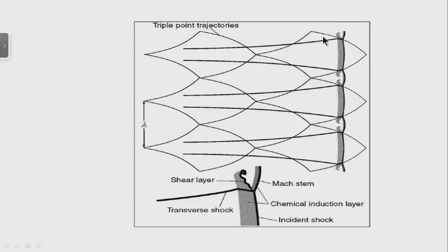Therefore, when the number of transverse waves is smaller than some limit, it is just not possible to propagate a detonation wave. In other words, if the number of cells of detonation in a particular region is less than some limit, let us say 3 or 4, regeneration of a detonation is not possible, because I am not able to get a multitude of transverse waves which keep on intersecting and keep forming these detonation waves, and that is one way in which the limits of detonability are formed.